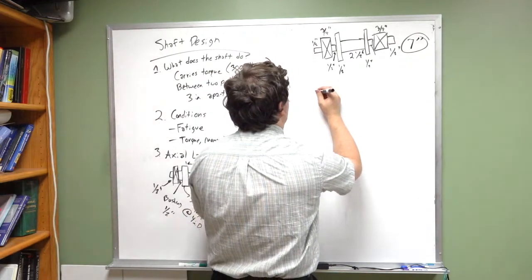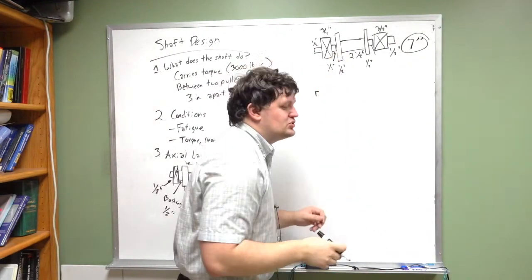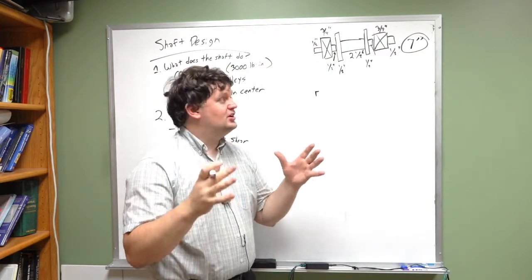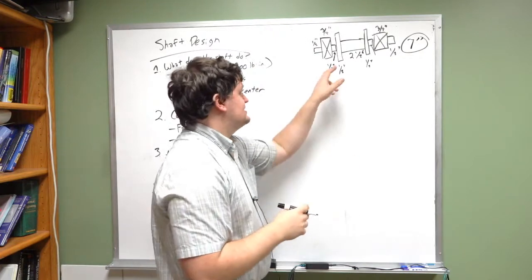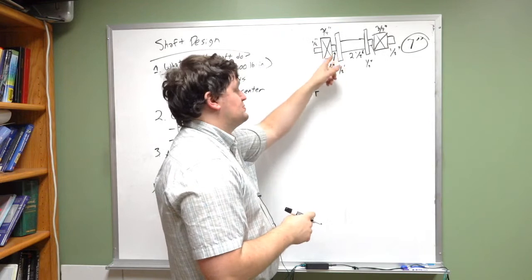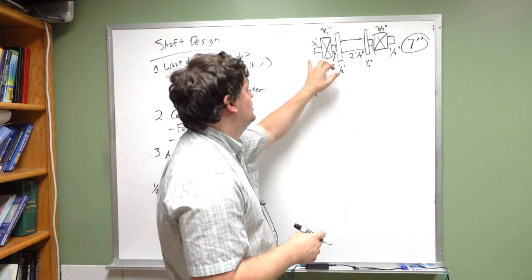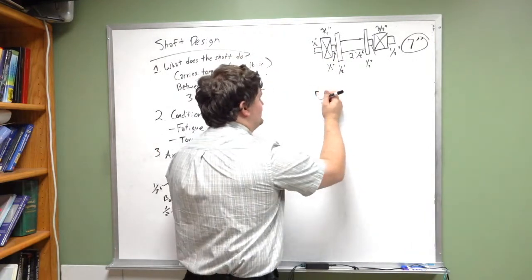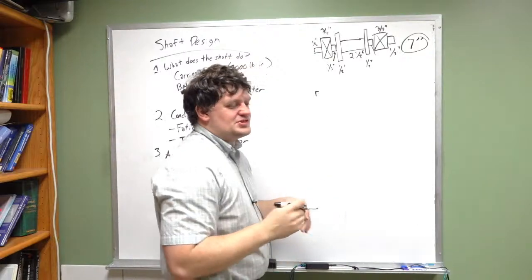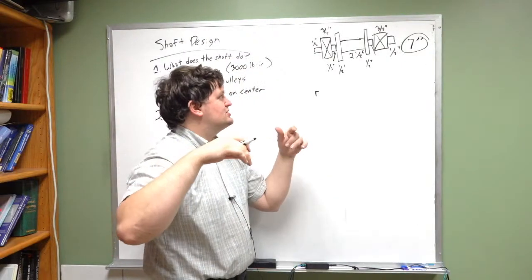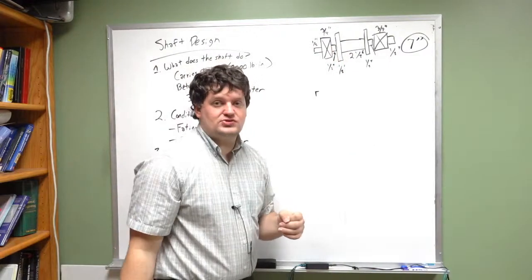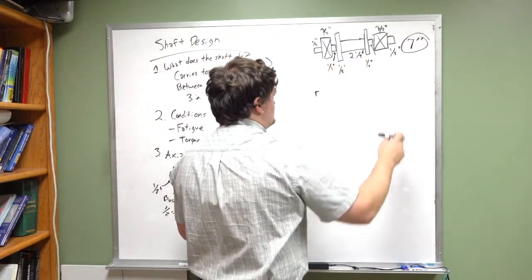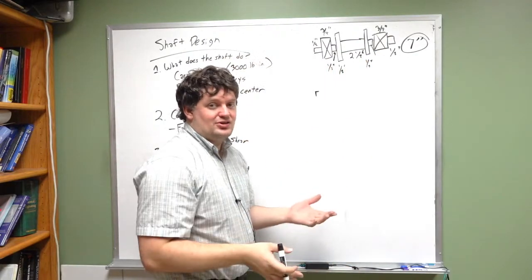Okay, so with this, I'm going to go ahead and take off the bushing. All the bushing does is it acts as a boundary condition that if any lateral loads exist on the pulleys, those pulleys will not move relative to the bearing. So that's kind of it. We're going to assume that the bearing uses a set screw, and by doing so, that means that you can exert lateral loads on the bearing directly, and it's not going to move. We'll assume that it uses a set screw on both sides, so that will handle any lateral loading.